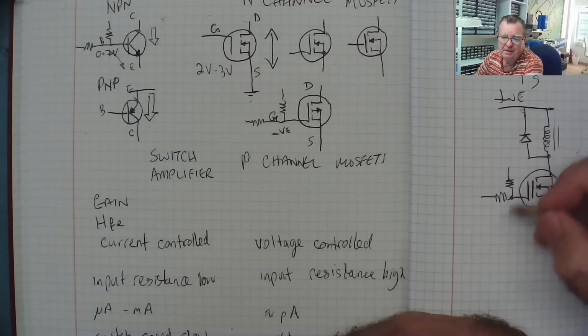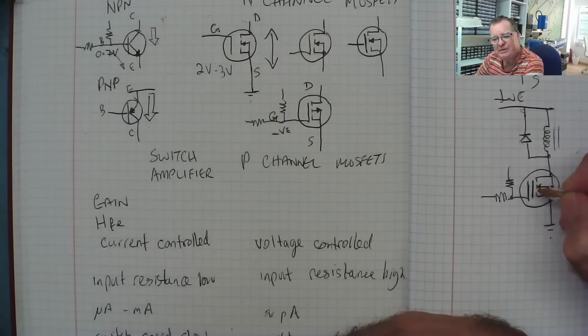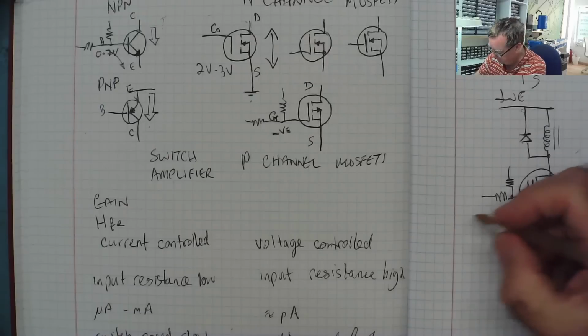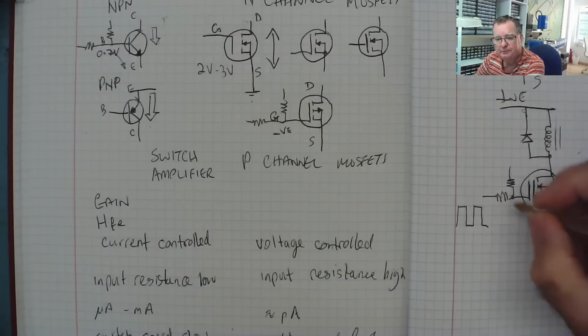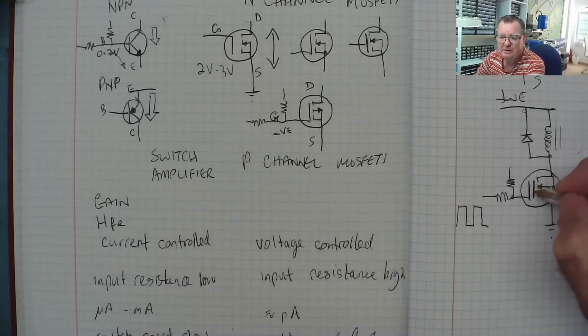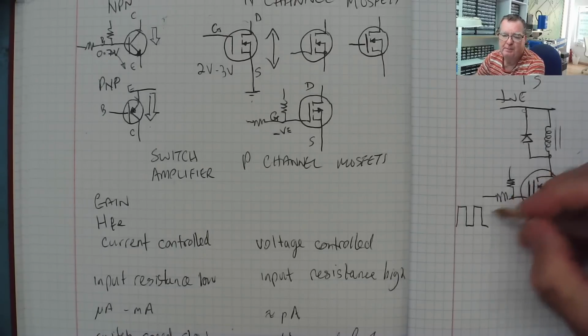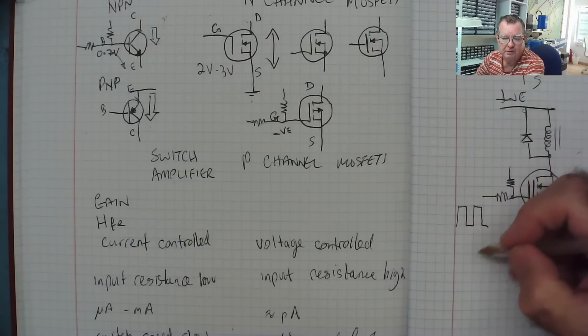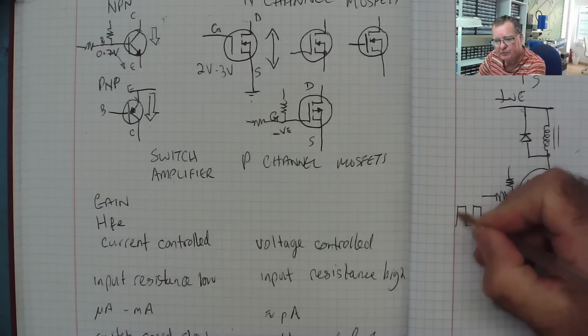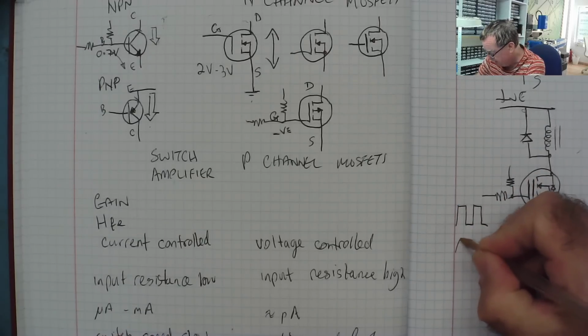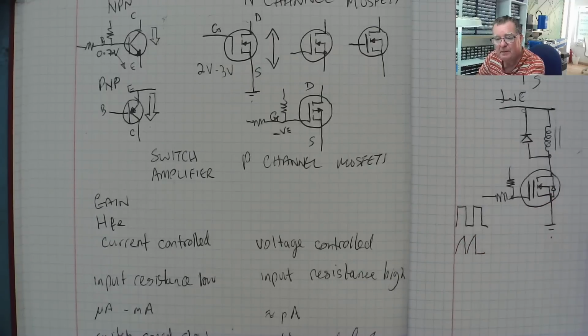When you get to high-frequency switching, that capacitor becomes a load on your switching device. So if you have some sort of driver sending pulses into here, the capacitor will effectively be charging every time you get a pulse and putting a load on the signal. And what that will tend to do is cause the signal not to rise straight up, but to rise up slowly as the capacitor charges. And end up with something like this, which is probably not what you intended.